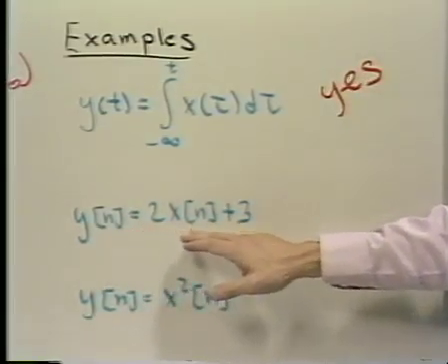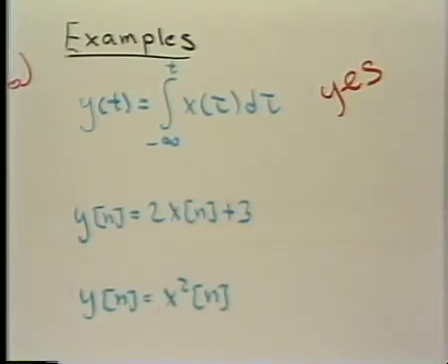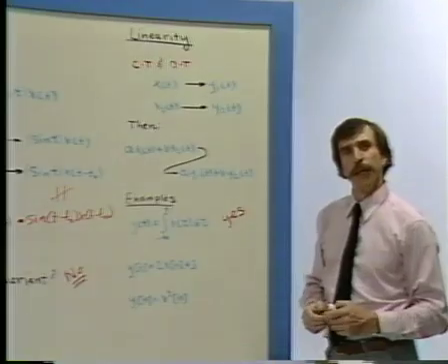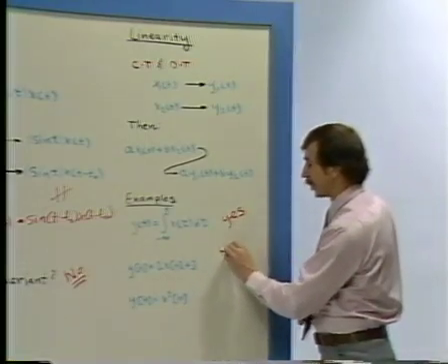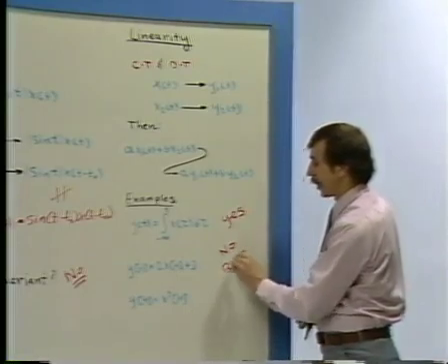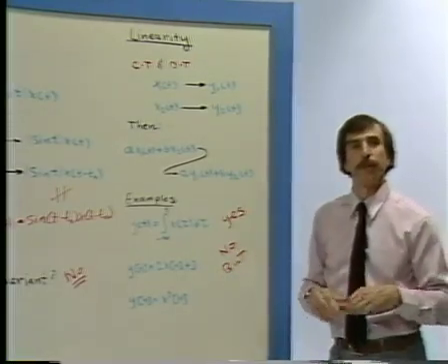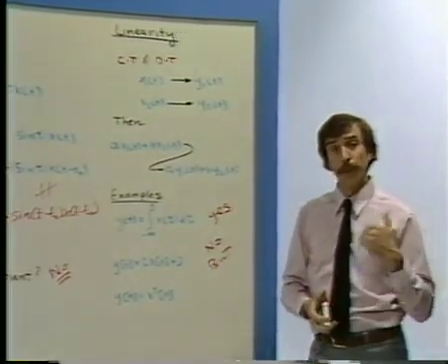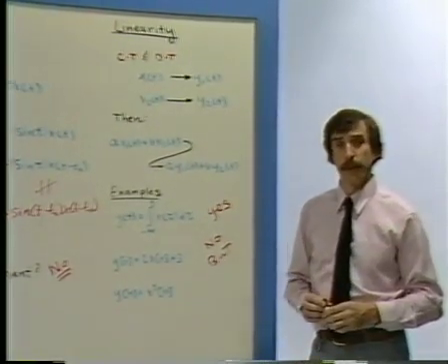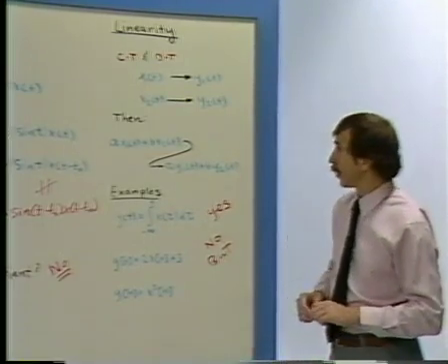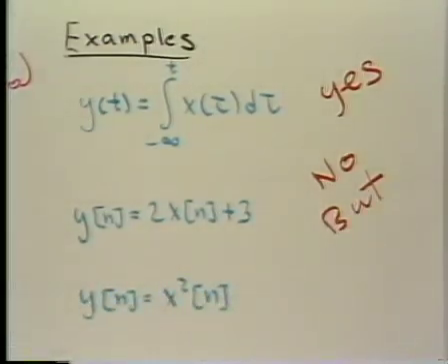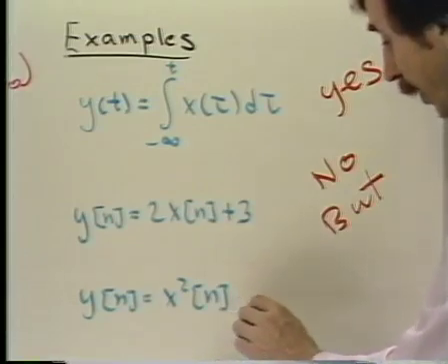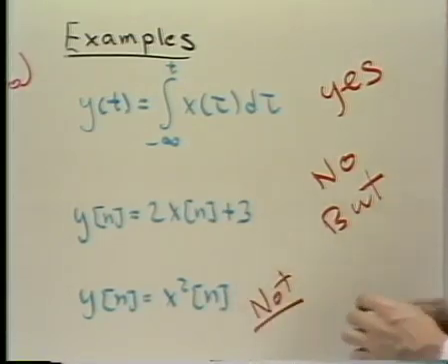This system in which the output is double the input plus a constant, you would kind of think is linear because it's a straight line, but one has to be careful, and in fact, as it turns out, this is not linear. There is a qualifier attached to it because it has a property referred to as incrementally linear, which is discussed somewhat more in the text. And finally, we have a system which is the squarer that I've indicated again here. And squaring is definitely not a linear operation.